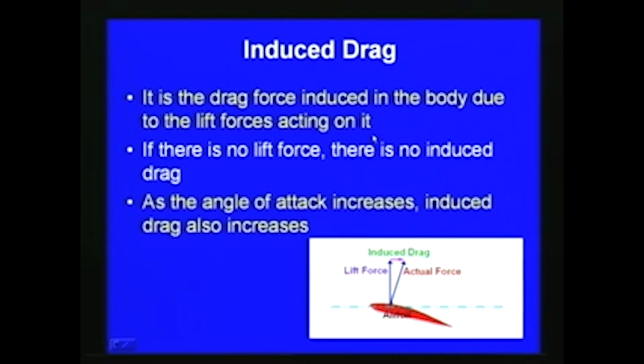Now, the induced drag is the drag force induced in the body due to the lift forces acting on it. We have seen that when a body is immersed in a fluid, depending upon whether the body is moving or the fluid is moving, we have the drag as well as the lift. This lift component may also induce some kind of drag, which is called induced drag.